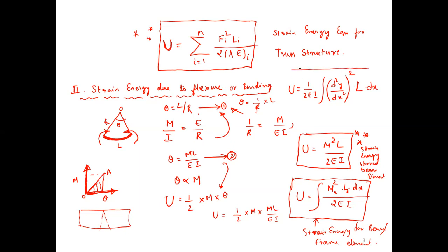So this is the equation for strain energy in framed structure or beam structure. Li, don't forget Li, because length is varying, right? Into dx, in terms of pure displacement. Any doubts? See, please keep a note. These are very, very important things. They will ask direct MCQ.